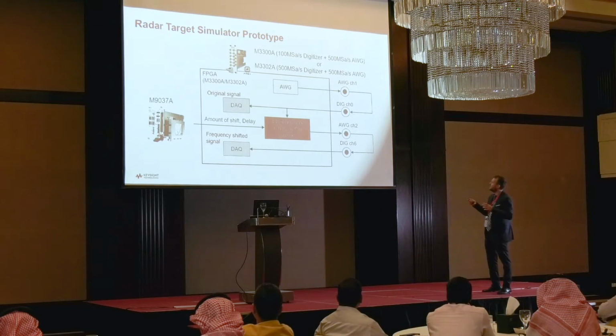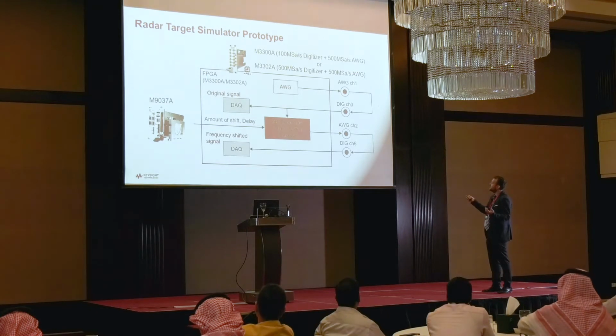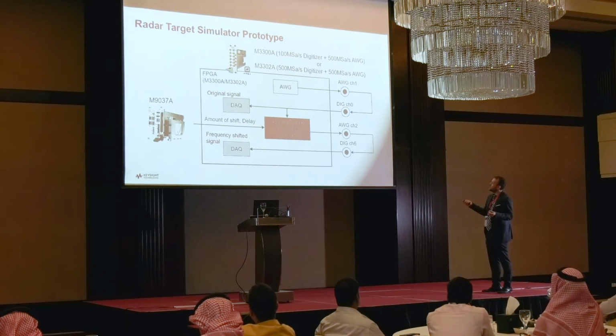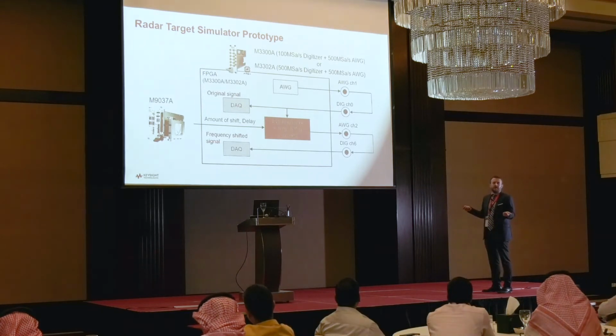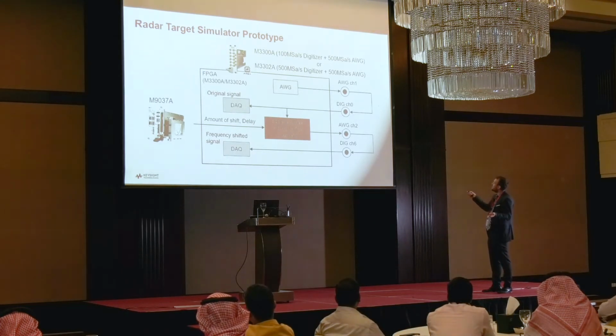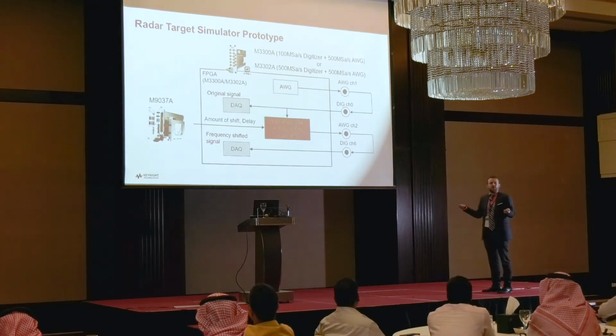for the module itself. And as a demonstration, we can actually use the AWG on board of that module to generate our radar pulses. We feed that back into a digitizer channel on the same module. We adjust it in time and in frequency before regenerating that pulse and capturing that on a further ADC. Now, what we can also do is take any other source and generate a pulse that goes directly into the module, and we can capture that output also with a scope.